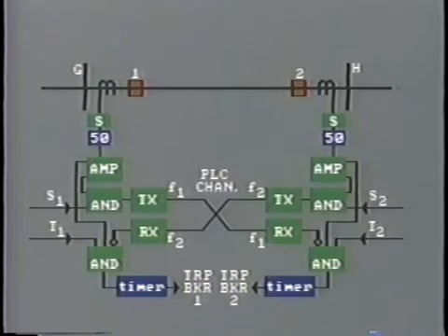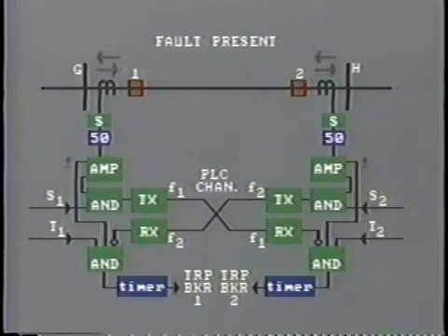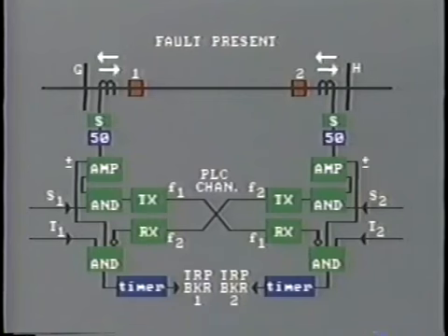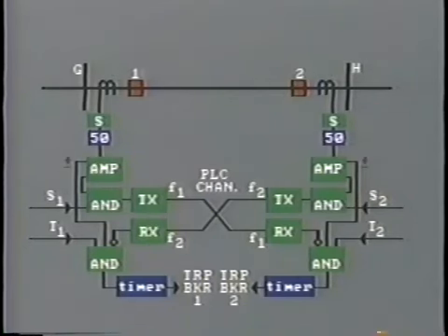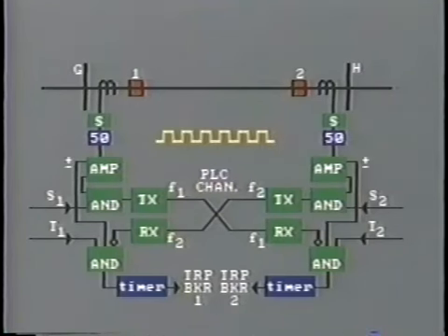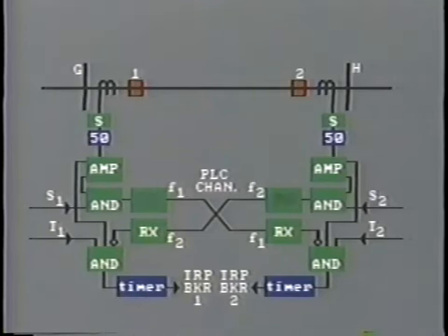As before, a special filter circuit is connected across all three CTs. If a phase fault or ground fault is present, this filter will produce a single phase voltage at its output terminals. The polarity of this voltage depends upon the direction of the current flow into or out of the power line. Actually, the voltage produced by the network circuit is not a sine wave, but a half-cycle square wave, like this. The transmitter is an on-off type, therefore a starting relay is required.